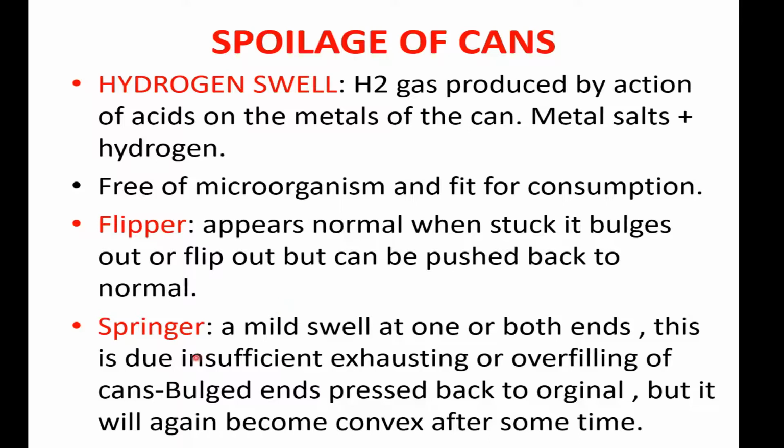Then what is a springer? A mild swell at one or both ends. This is due to insufficient exhaustion or overfilling of the cans. The can is bulged but can be pressed back to the original. Once you push it in, it goes to normal, but after some time, just like a spring, it springs out again and bulges out. So that is called a springer.